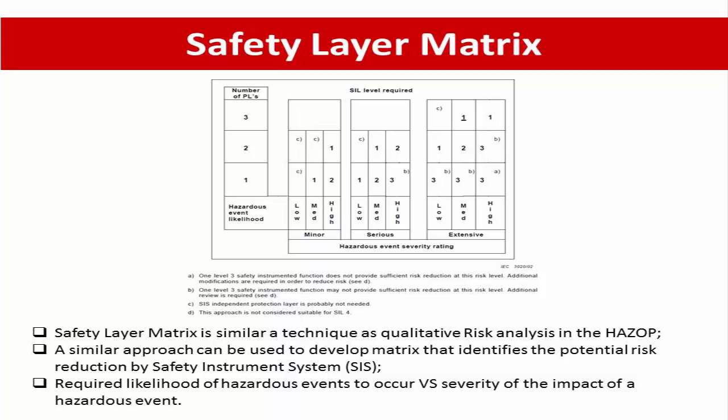So after the hazard study has been performed, the risk associated with the process shall be evaluated with the expertise of the plant personnel and other hazard and risk analysis specialists to identify potential hazard events and evaluate the likelihood, consequence, and impact. A similar approach can be used to develop the metric that identifies the potential risk reduction by a safety instrumented system